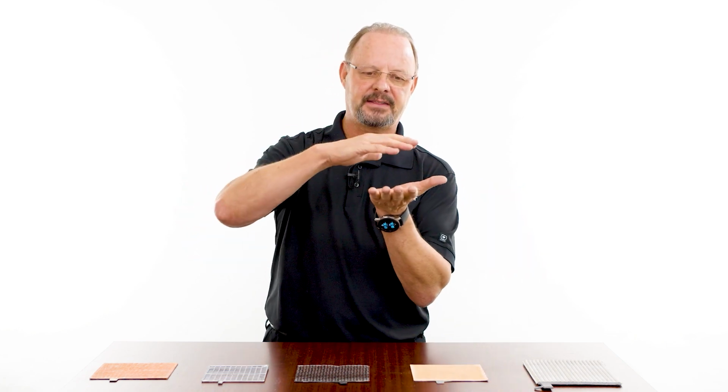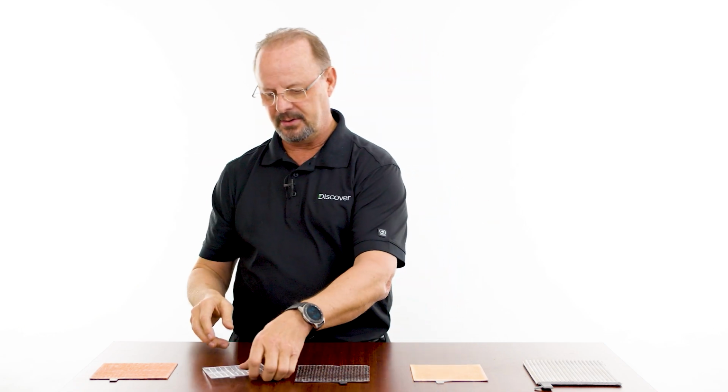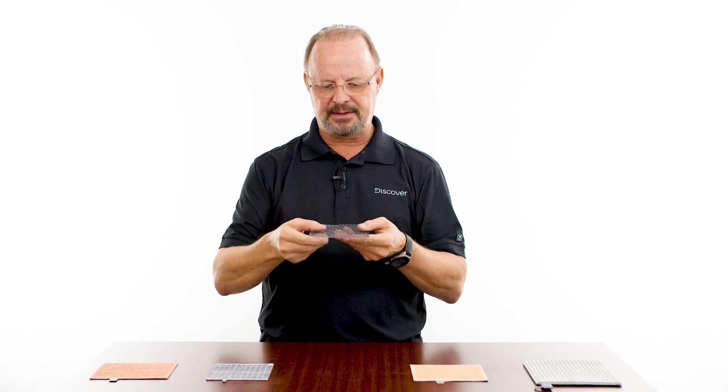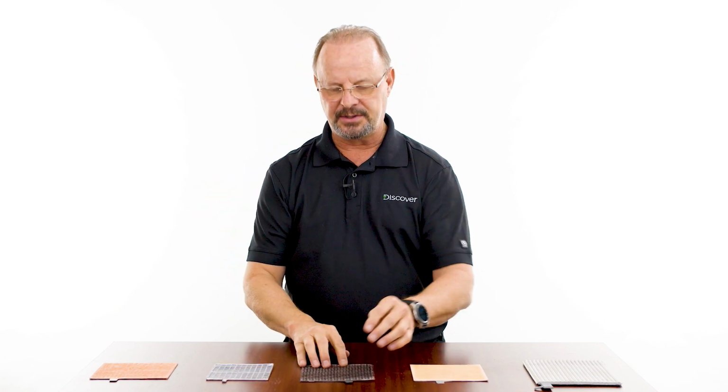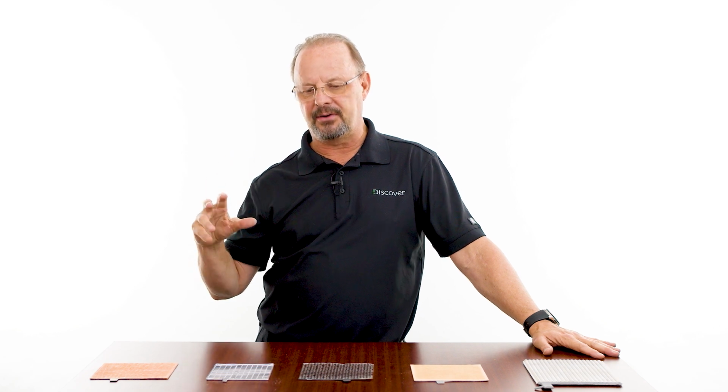So think of the battery production process in terms of speed, and in terms of tensile strength, the ability of the plate to hold paste as it's being pasted onto the plate. If this plate is ripping through those pasting machines at 250 meters a minute, it's pretty easy to comprehend that it's not going to be able to hold a lot of paste. And that paste is going to have to be pretty wet, or you're not going to be able to run those plates through there very fast. So the grid wire design will determine the effectiveness of the adhesion of the paste, the overall efficiency of the plate during curing, and the overall cycle life of the battery later on.